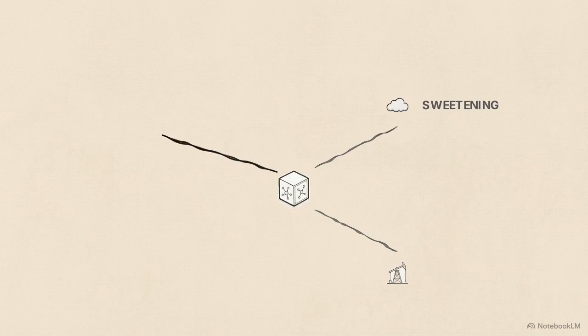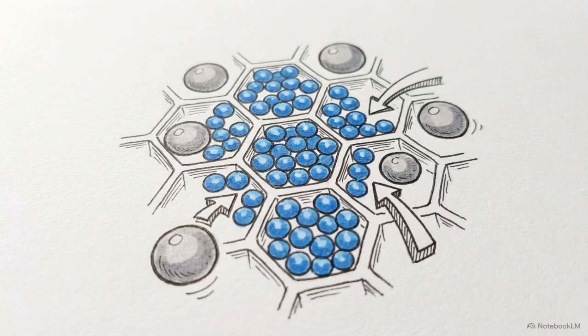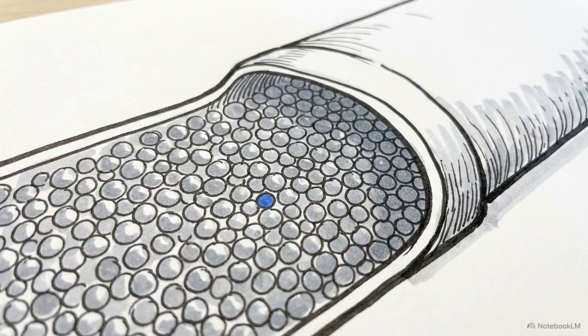Next, draw a crossed-out water drop. The incoming gas is saturated with water, which is routed through molecular sieves. Molecular sieves are vessels filled with crystalline materials that trap specific molecules based on size. They reduce the water content to less than 1 part per million.